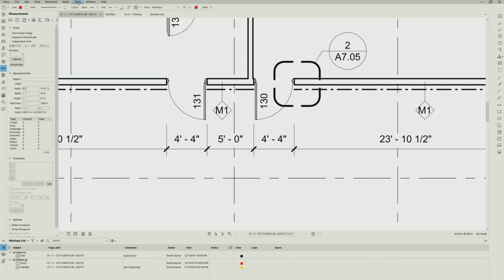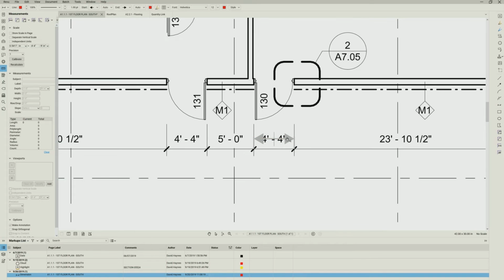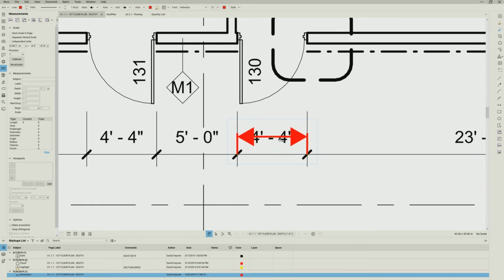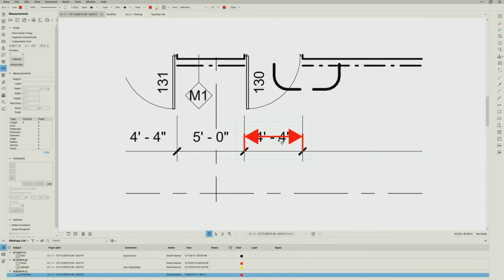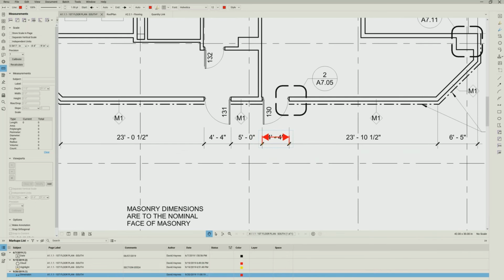And that's done with the tools. And let's come up here to dimension right here under the markups. And this verify. Again, because I'm snapping to content, this should work out fairly well. And now this shows that I'm hitting to it and it's 4'4". I'm in good shape. All right, so we've calibrated.